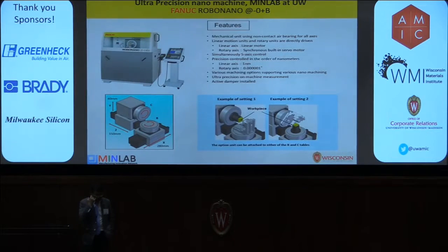And actually, this Sunday, I am bringing this machine from Japan, the first time in the USA. This is the 5-axis ultra precision nano machine, which means it has 3 linear axes and 2 rotary axes. Each linear axis moves 1 nanometer, and the rotary axis moves 1 microdegree. Basically, you can create all kinds of features with precision, talking about the semiconductor manufacturing process level.